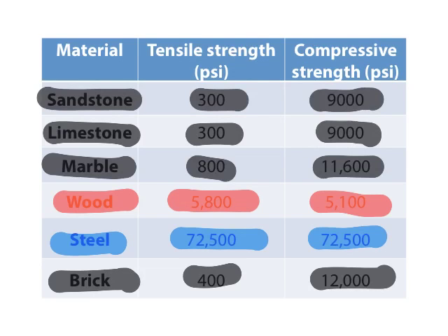compressive and tensile strength. Now a thing to note here, we have another very common building material that's not represented in this chart, which is concrete or reinforced concrete. The way to think of concrete is like stone. It's very, very strong in compression but weak in tension. And as we're going to see, reinforced concrete actually contains steel in it. So really it's a mixture of stone and steel, and that way it has both compressive and tensile strength.